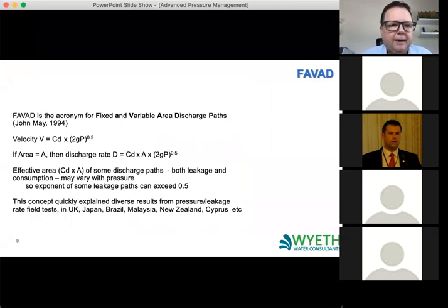Now, it was back in 1994, John May, I believe, who came up with the acronym FAVAD, F-A-V-A-D, which stands for Fixed and Variable Area Discharge Paths. And this basically was a formula which said, okay, the leaks in my utility are a combination of the fixed area and the variable area.